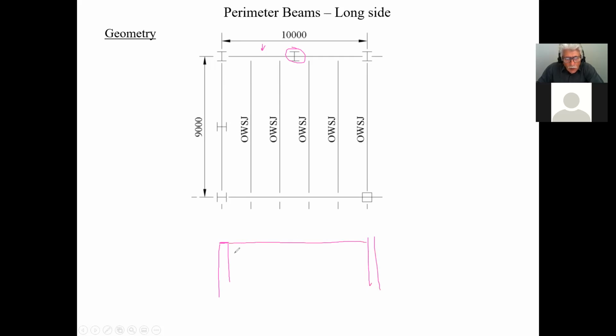And then we are going to learn how to design the connection from the beam to the column. And here where the wind column is, it's really right underneath, almost like a girder system. It's underneath, okay? And we'll talk about this next week. This is called a cap plate. So basically this becomes a continuous member, supported here, supported there, and supported there. And now the span is, this is 5 meters.